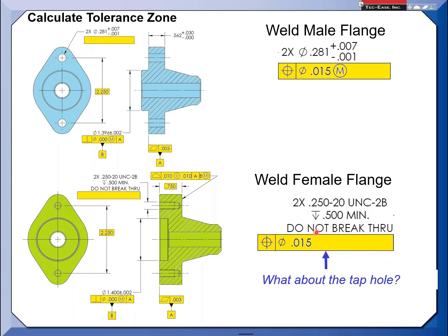Yeah. So in this case, you're going to see the solution here. There's not an M on the thread, but I'm not grading on that. If you didn't put an M or you did put an M, I'm considering both answers equal. Putting an M here, as far as I'm concerned, means I can build a hard gauge to qualify the tapped hole. Literally can build a gauge to show representation of that. I'll have an example coming up shortly showing you that. So with that being said, there could be an M here or may not be an M, depending upon companies' policies or practices. But right now, if you put an M here, I accept it as good to go.